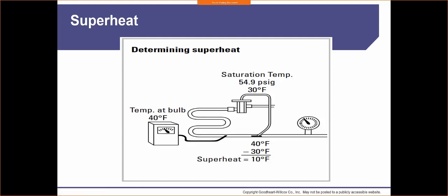Why is that important? It's important because if I don't have all this heat being absorbed here and it's so close to the saturation point, there may be liquid that's still left. We haven't crossed that boundary, and there's the potential of having that liquid get into our system, into our compressor. The compressor doesn't like liquid. It's not going to compress it. We're going to have issues, and there's going to be potentially a malfunction.